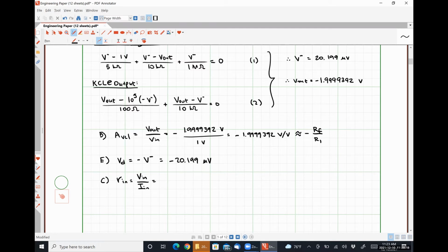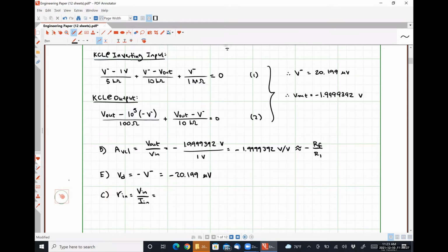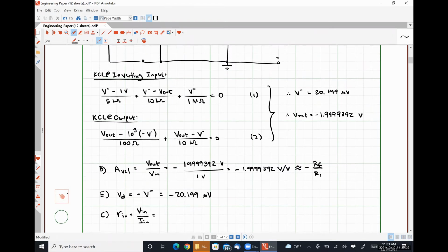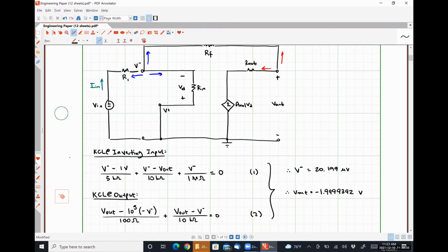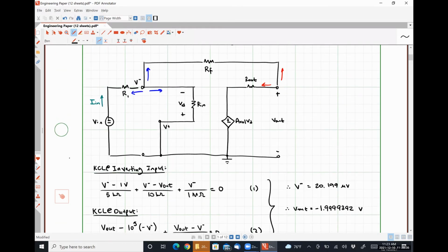All right. So we're just looking for the Thevenin equivalent when we already know what the open circuit, or excuse me, what the voltage is there. Okay. All right. So how do we determine what IN is? The voltage drop over R1 divided by the resistance of R1, right?